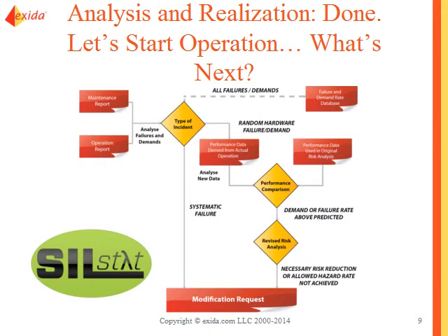Quite often, information doesn't get recorded unless there is a work order associated with it. So if you have a problem with a transmitter and you can solve it by simply rebooting the transmitter, that most of the time doesn't get recorded, and that could lead to very optimistic conclusions about the failure rates of your transmitter. There may be a serious systematic issue that you get rid of every, let's say, 3 months by rebooting that transmitter, but that may be an indication that the transmitter is not suitable for your application. All right, so we need to have data, and we need to be able to compare the data to our assumptions.